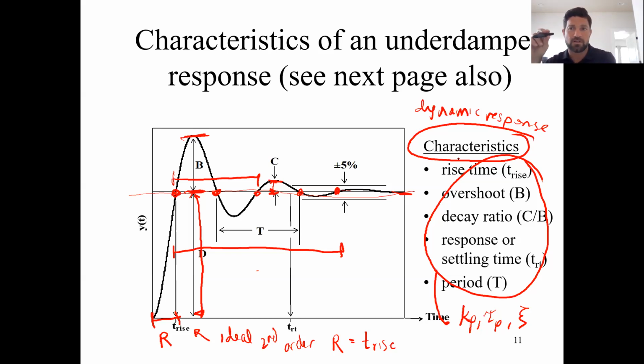There's a homework question on this that is extremely important to do. I want to point out that there's only one subtle difference between a second order process and a second order plus dead time process. If you're given the transfer function, you know there's a dead time, so you treat it the same way as a first order.